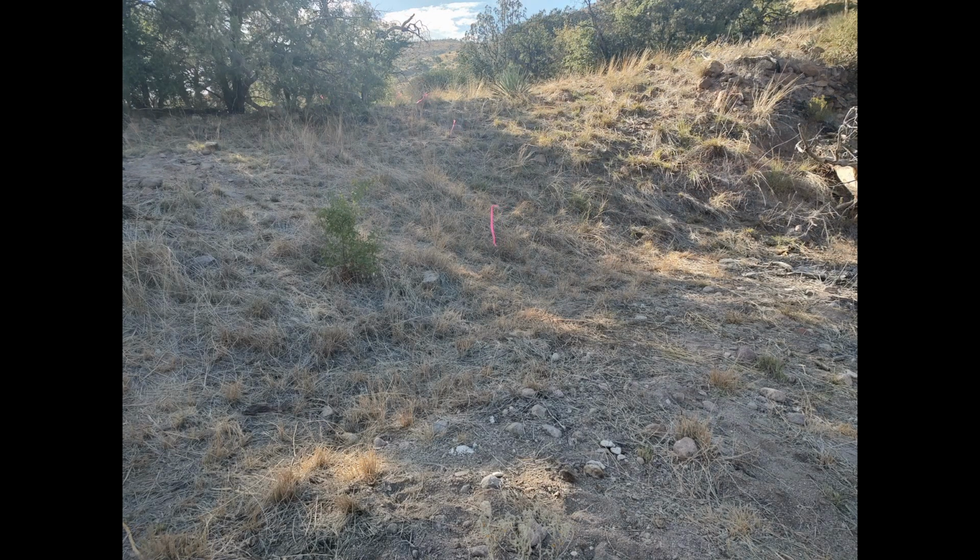To build the new spillway, it will be necessary to dig 7.4 feet deep through a narrow ridge where the end of the dam ties into the high side of the valley. We examined this ridge for the presence of bedrock to make sure it would be possible to dig through the ridge without the need for a hydraulic ram attachment on the excavator.